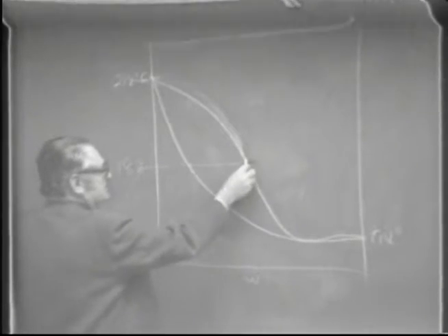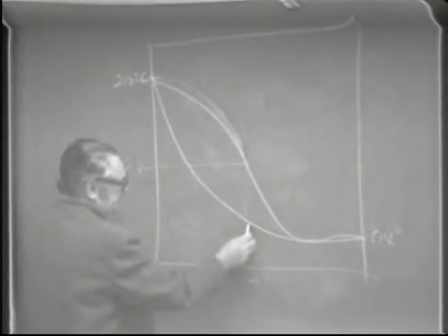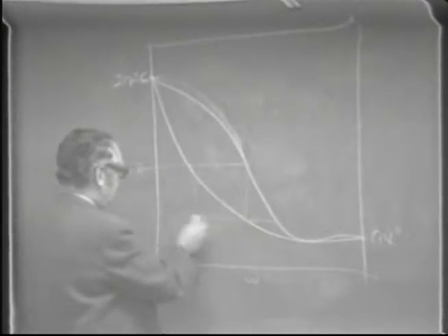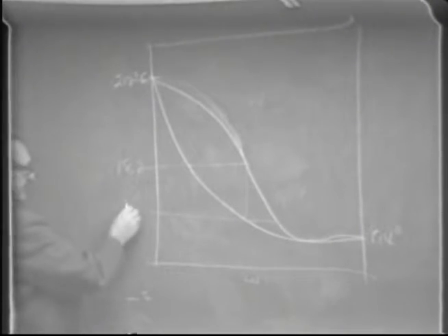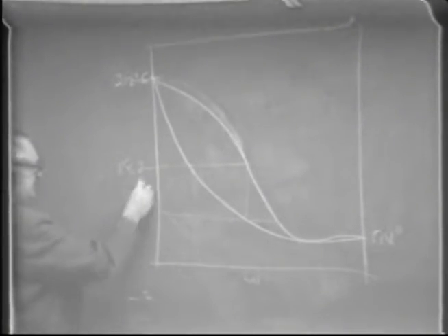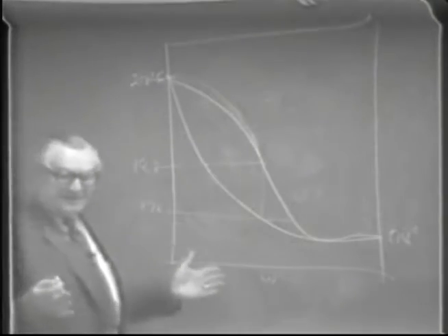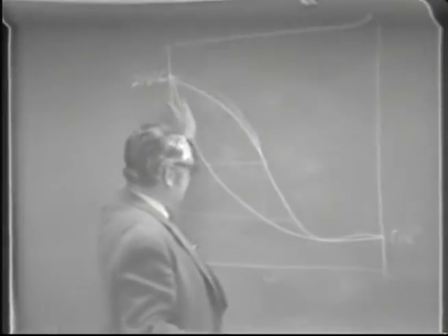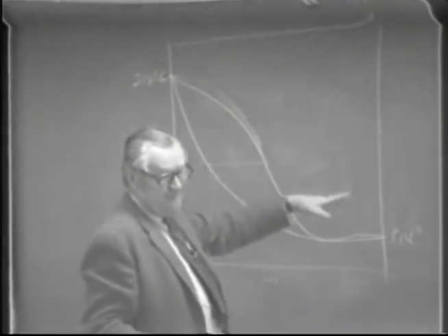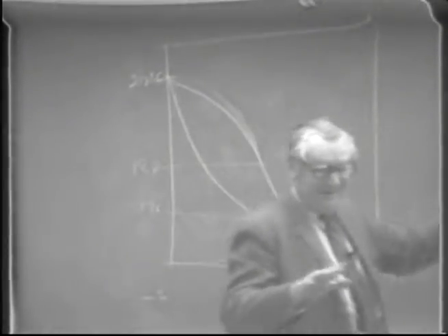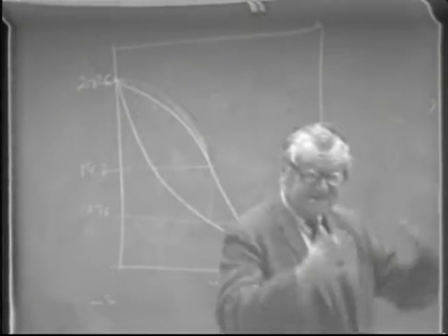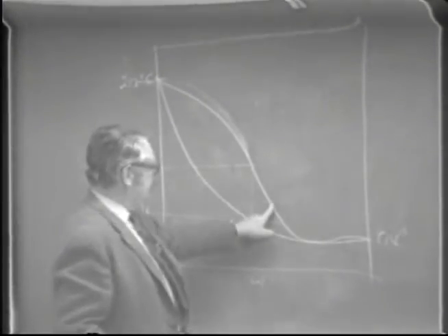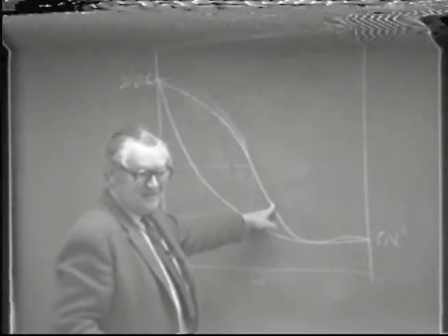The way I've drawn this, in effect, at equilibrium, you'd get this much change here in one tray. That'd be down to about maybe 176 here, just one ideal tray step. Now this, of course, doesn't take into account the reflux ratio. We have to revert to the XY diagram, the McCabe-Thiele type diagram, to take into account the reflux ratio. But anyway, it might be that much in one step.